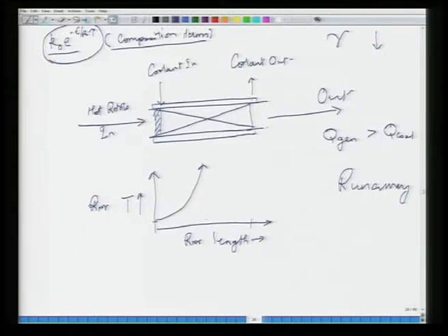Well, let us say you got a highly exothermic reaction. Because it is highly exothermic, if you increase the inlet temperature just a little bit, reaction rate actually goes up a lot. Because the reaction rate goes up a lot, the amount of heat that is generated goes up a lot, amount of heat that is being removed is about the same.